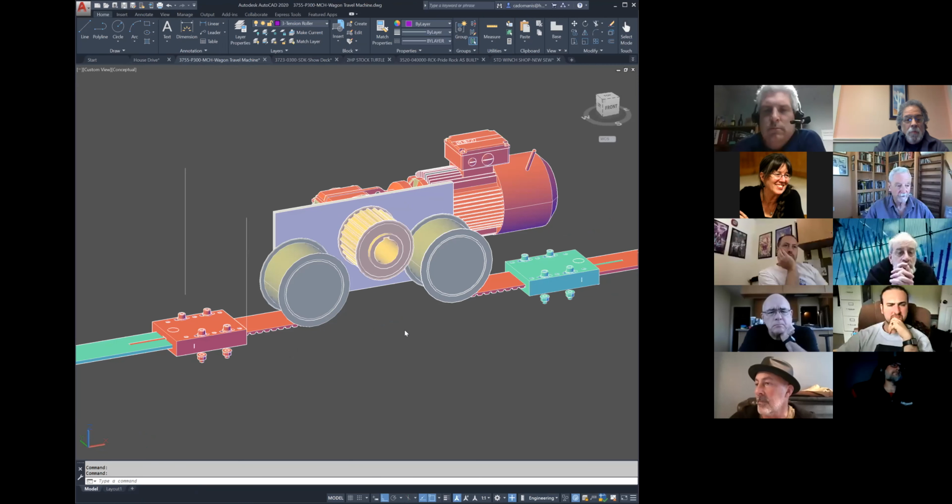What makes the advantage of these super simple is you just stick a sprocket on a motor and put the timing belt around it. You have some means of tensioning it, often on the opposite end. The dead end usually can move and tension the belt. And it's very accurate because there's no slip involved at all.